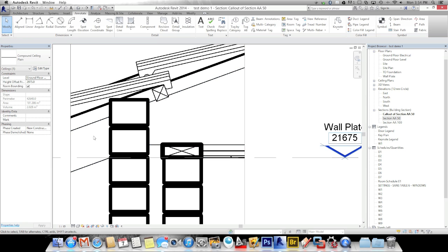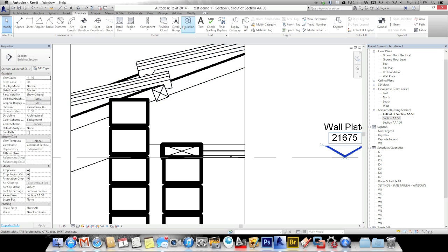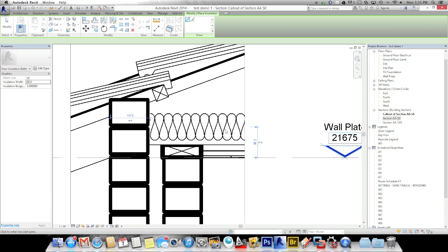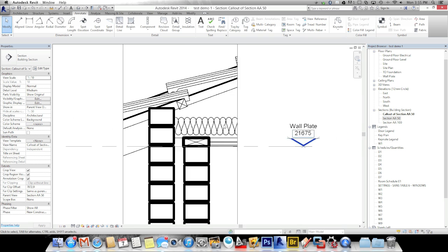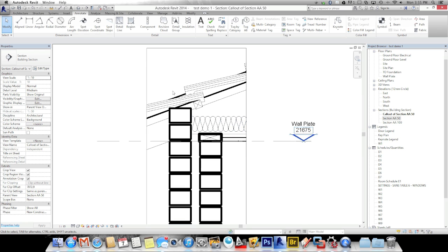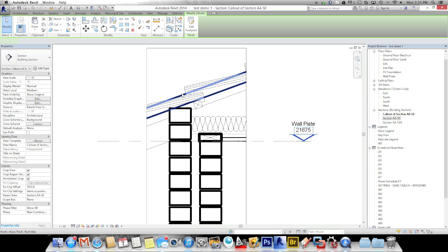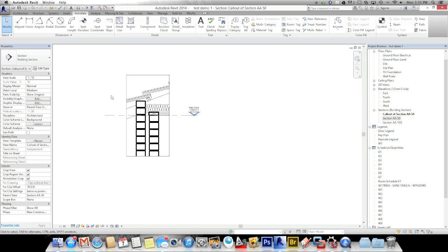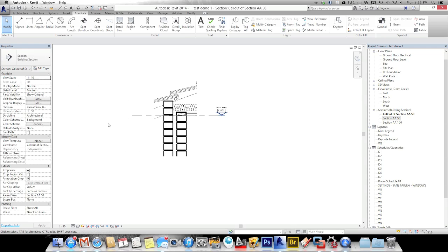We've got a truss going through, detail, and we're going to add some insulation. And you will add text to that as you wish. Let's just hide the roof. And there's a very quick 1 in 5 detail. Let's just hide the crop line, and there we go. So that's how you draw detail callouts or extractions.